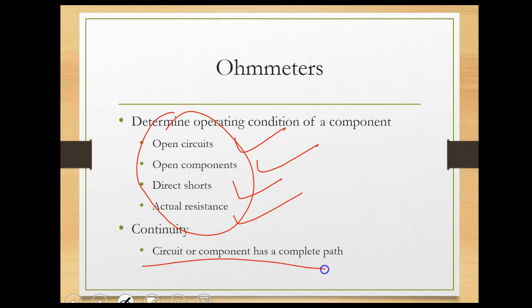Continuity is another function based on resistance, but sometimes it could be a very small resistance where you see maybe nothing because the amperage you're putting in is not being received well in the multimeter, but it will give you continuity. So the resistance may be 0.0001 ohm, but if you have continuity, you can probably hear the beep.